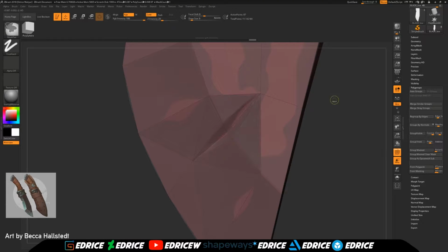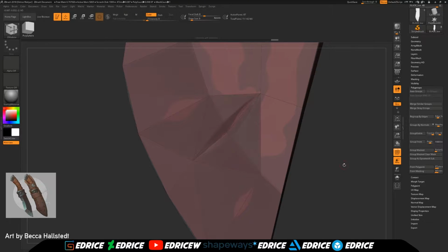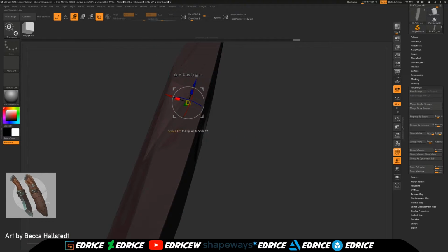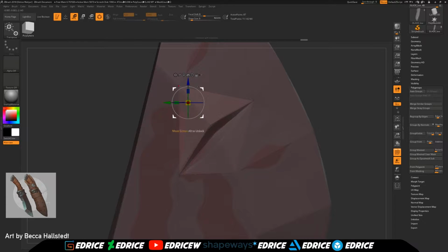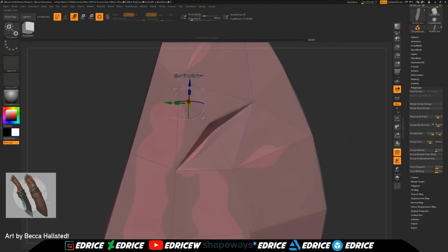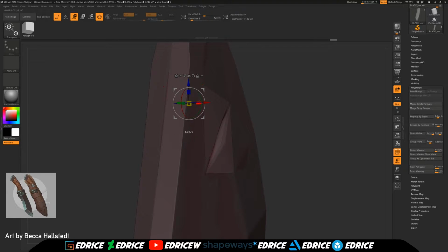So we're going to mask only the verts we want to edit, invert our selection. And then with the 3D gizmo that we're going to unlock, when you hit that lock, you can move your gizmo where you need it, then lock it again, and now you can actually edit it. And we are using the scale to push those two verts apart, since they're symmetrical. And then we are moving them into position, and we're going to do the same thing for those bottom two verts.